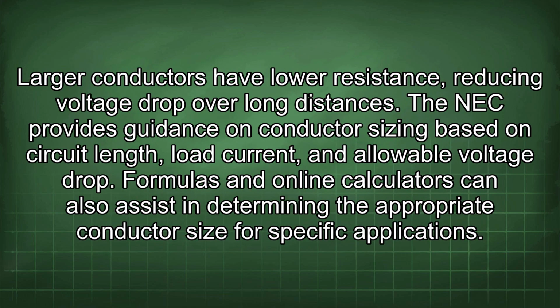Larger conductors have lower resistance, reducing voltage drop over long distances. The NEC provides guidance on conductor sizing based on circuit length, load current, and allowable voltage drop. Formulas and online calculators can also assist in determining the appropriate conductor size for specific applications.